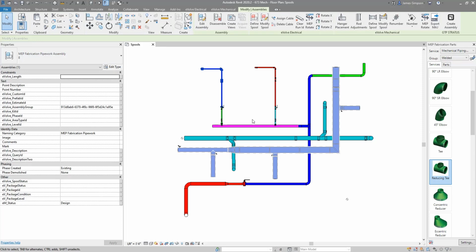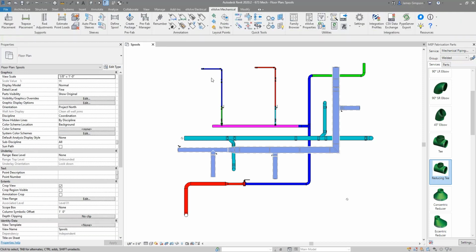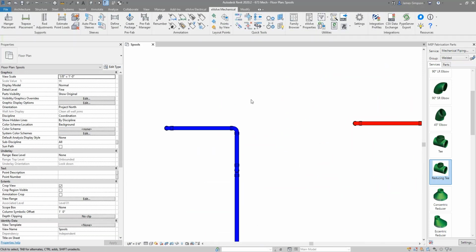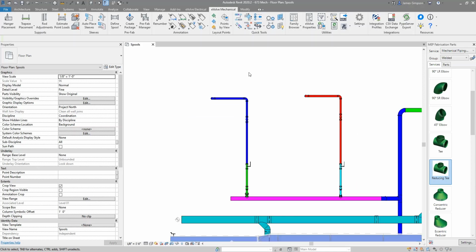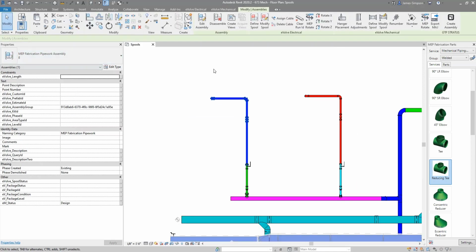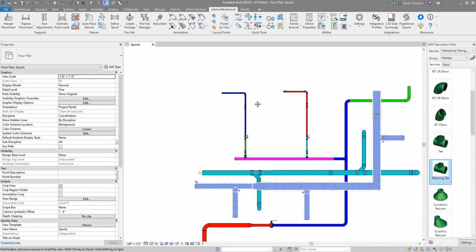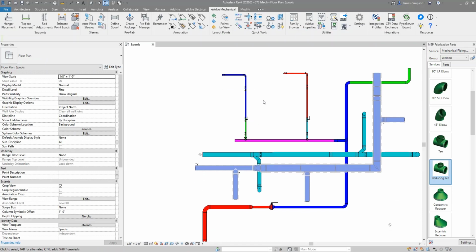And if it's a simple change to something that's existing, we can use modify spool. But what if it's an addition? If it's on the end of that sequence, this could just become 9, and that makes it easy. But when you have additions that are in the middle of that sequence, such as right here, maybe it's a sync drop piece of equipment, you actually have to have a change in number sequence all the way through that line, right, to reflect that addition.